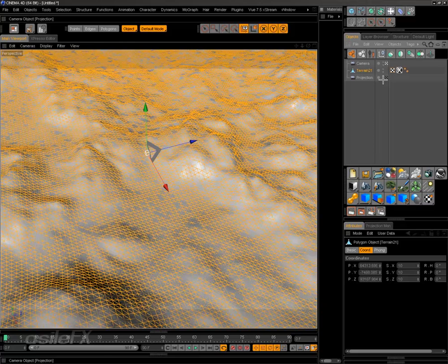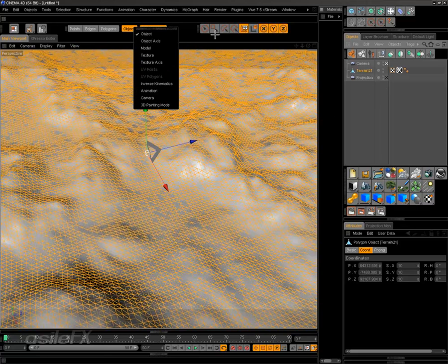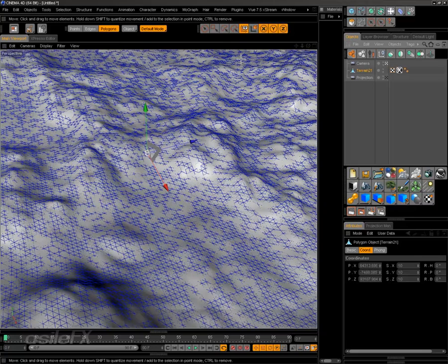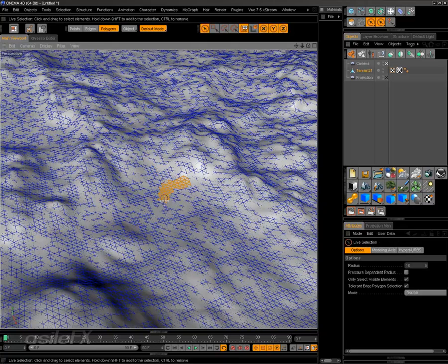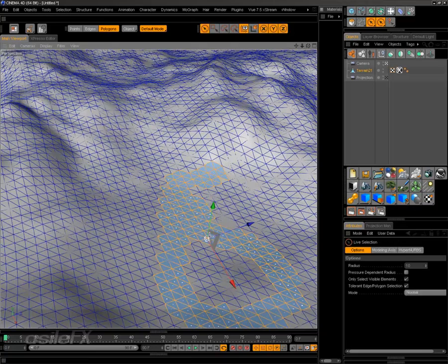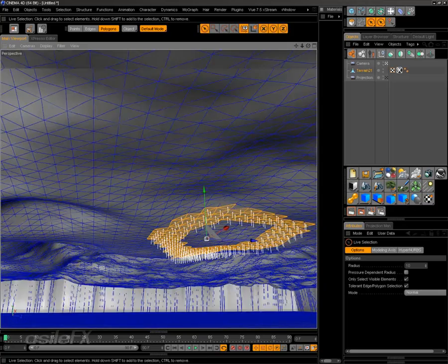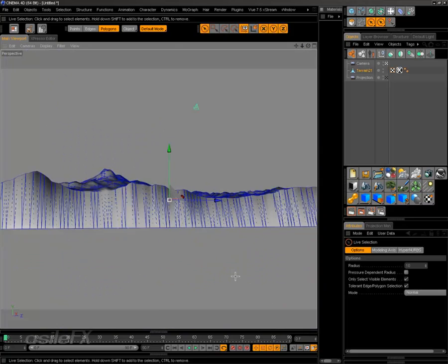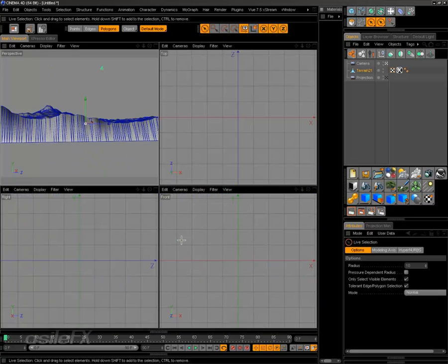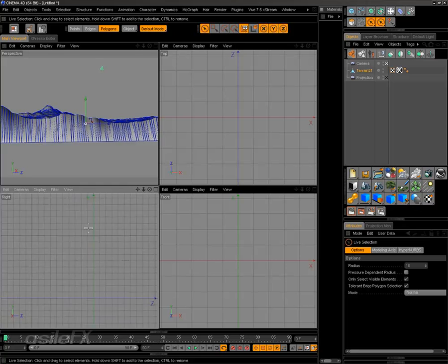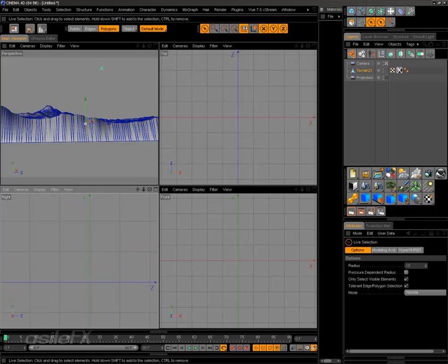and the terrain itself, I do want to check and make sure, and we're going to go over to the polygon mode, that the normals are facing the correct direction, and we can see that they are facing down. And we also have all that extra geometry on the bottom, which is normally something that would only happen during the terrain export.